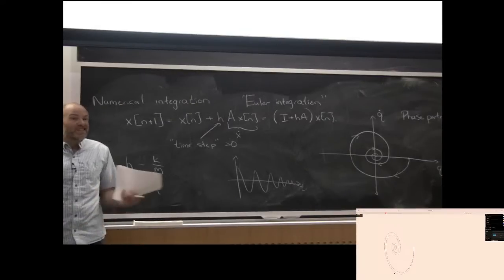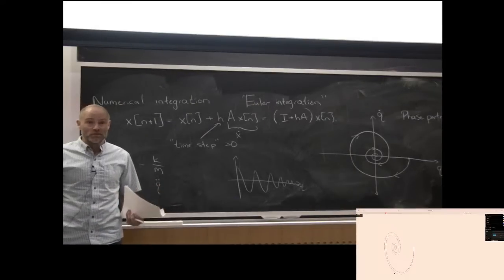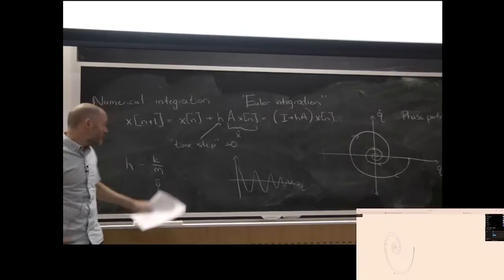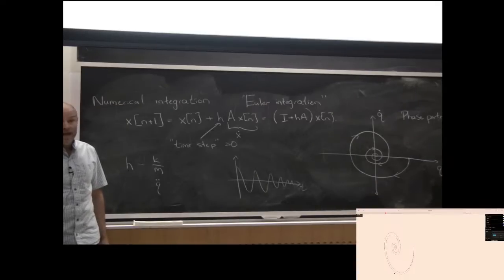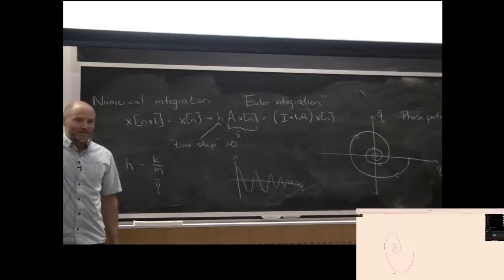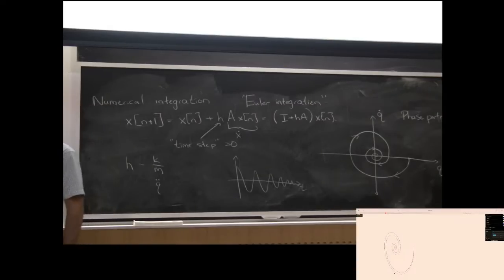But actually, the accelerations are relatively low. So big forces on a big robot are kind of okay. When Atlas goes to pick up something like a toothpick, that's the bad case. You get big forces on a little mass, and you send toothpicks flying in your simulator. And it turns out robot arms picking up stuff are not so different from that. The range of inertias that you have to deal with in manipulation is the first challenge.